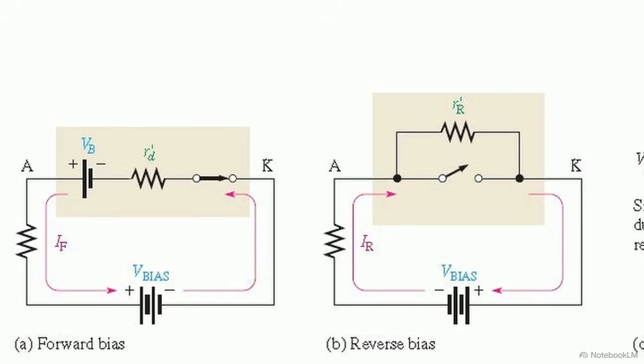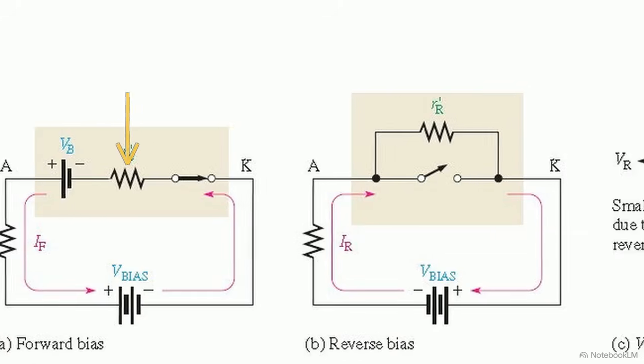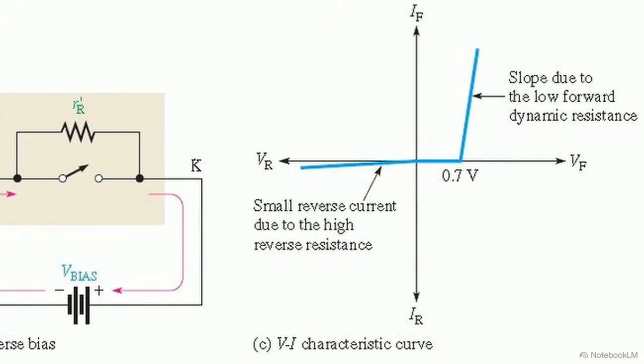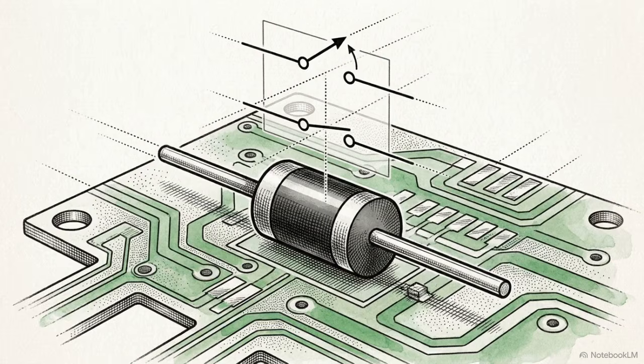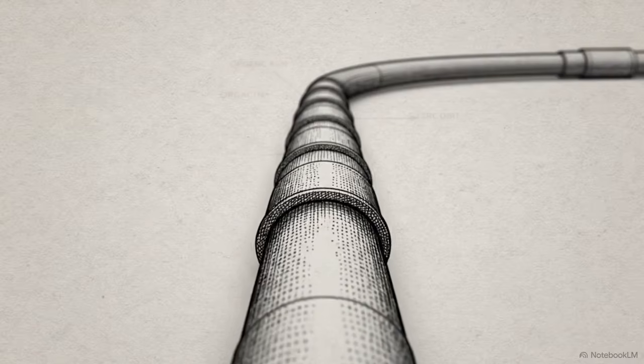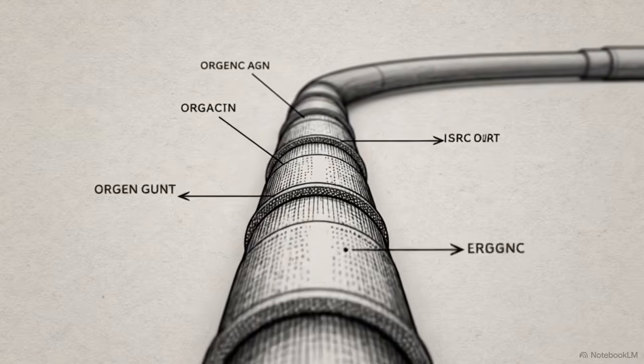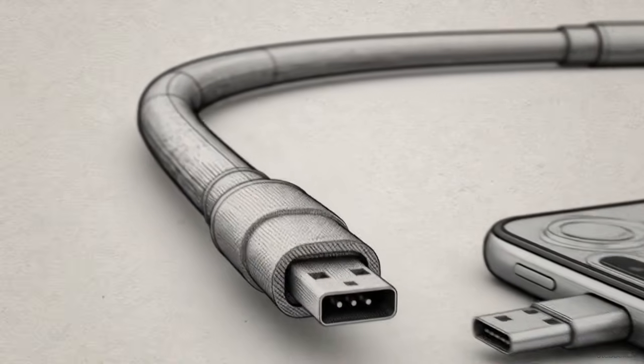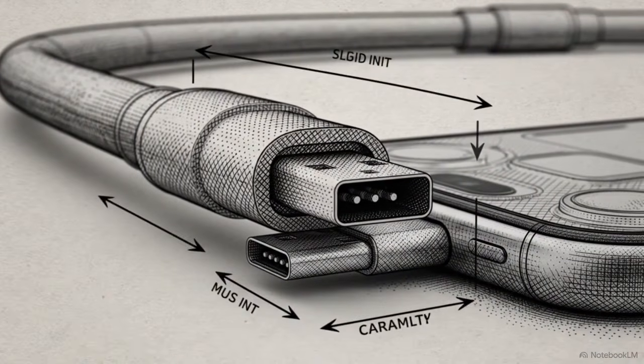Finally, this visual shows the complete model. It adds a small resistor to the circuit, known as forward dynamic resistance. Here, the upward line is slightly sloped to account for voltage increases as current rises. This is reserved for high-precision design. Effective engineering is the art of choosing a mathematical model that sacrifices just enough quantum reality to achieve maximum practical utility.